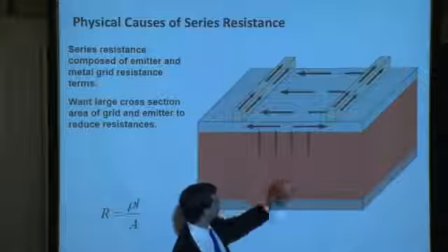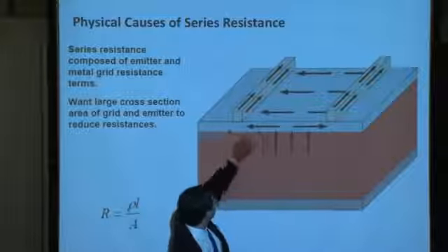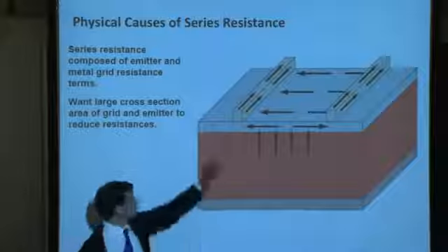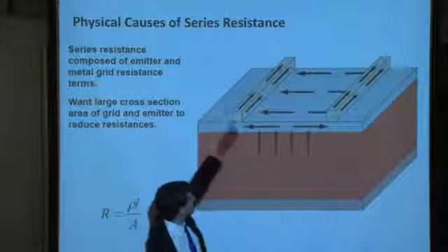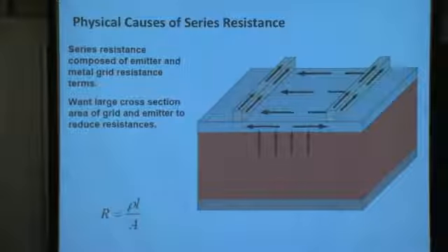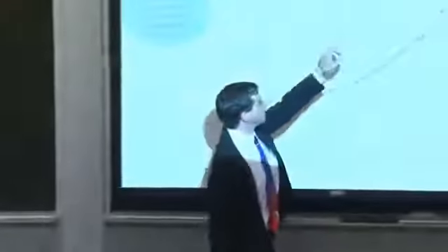We have the series resistance of the bulk, we have the series resistance of the emitter, and then we have the series resistance of the contacts as we contact the device, and then the series resistance within the contact itself. So at least 4 different components of series resistance in our device that are all lumped together when we express our IV curve in this manner, we lump them together in that R sub S.